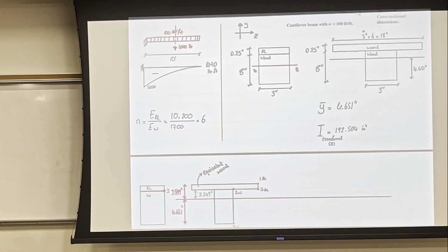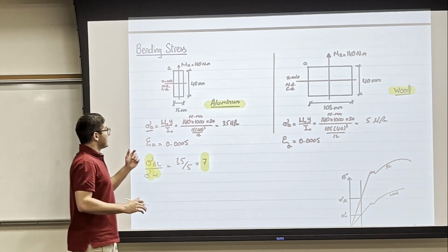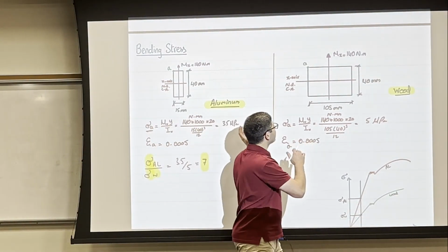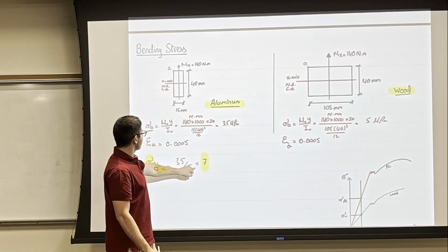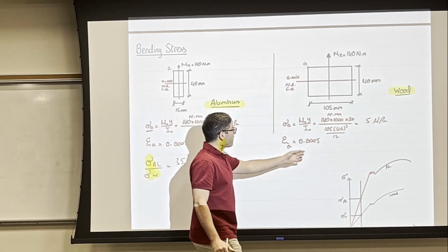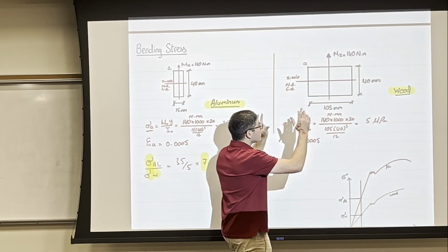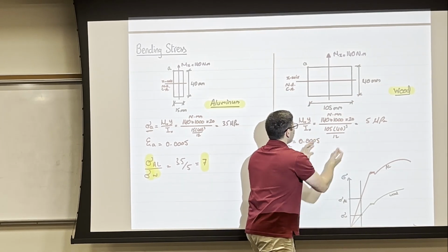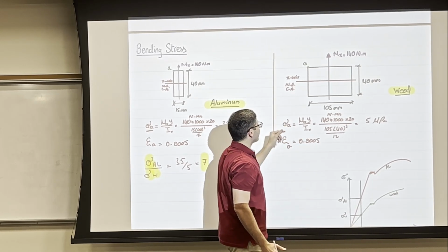And if you remember, from practicing the concept, when we found the equivalent wooden section, there was a difference by a factor of 7. So we got very low stresses here, because of course we increased the area. When we increase the area, we have a very big I, which is the moment of inertia, and therefore we had low stresses.